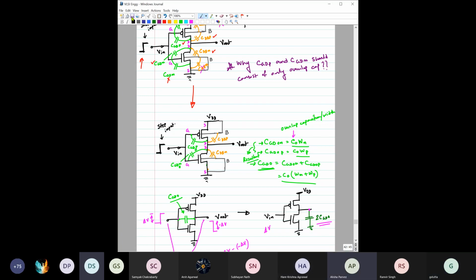There should be no gate-to-drain channel capacitance because we know one of them is cutoff region. Yes, Alicia, very good. Because these two capacitances are between gate and drain, as I mentioned, for most of the region the transistor is either in cutoff or in saturation. So in both cutoff and saturation, the gate-to-channel component associated with the drain side becomes equal to 0.